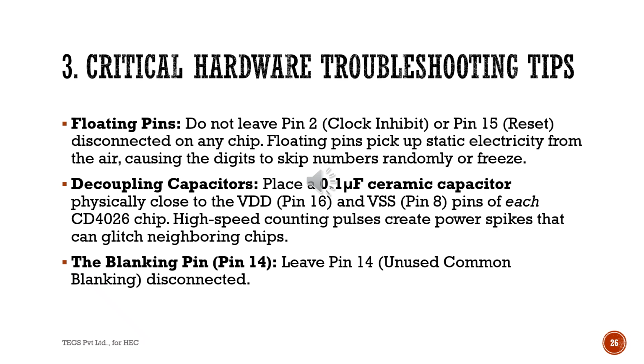Decoupling capacitor: place a 0.1 microfarad ceramic capacitor physically close to VDD pin 16 and VSS pin 8 of each CD4026 chip. High-speed counting pulses create power spikes that can glitch neighboring chips. The blanking pin, pin number 14: leave pin 14 unused, common blanking disconnected.